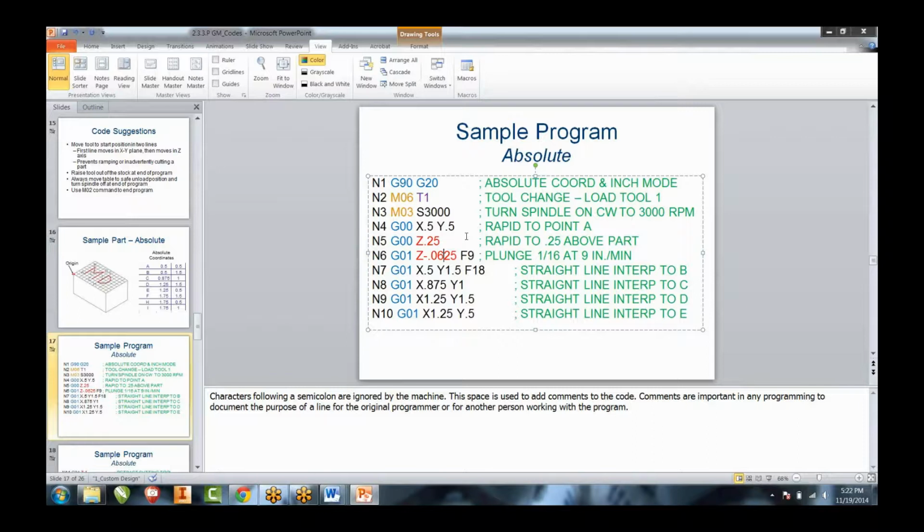When they're doing the initials, I don't go deeper than a 1/16 of an inch. That way, if there is an accident and they screw up, I just face the top of the part off and we do it again. There's no point in really going that much deeper into the material. We're just trying to cut it in.